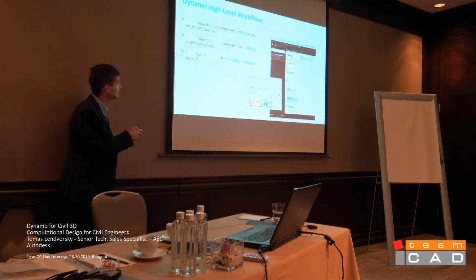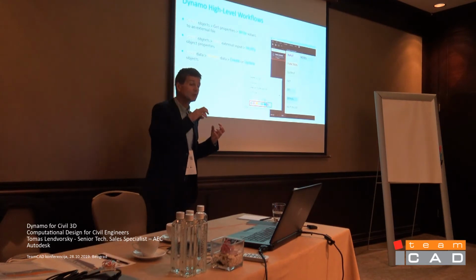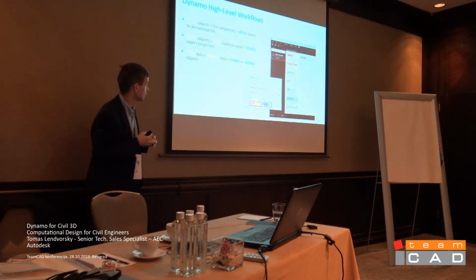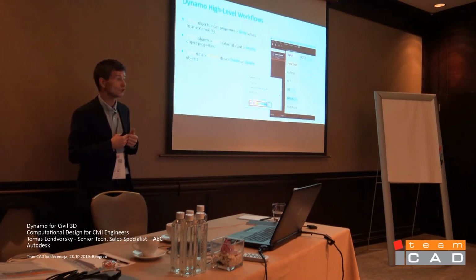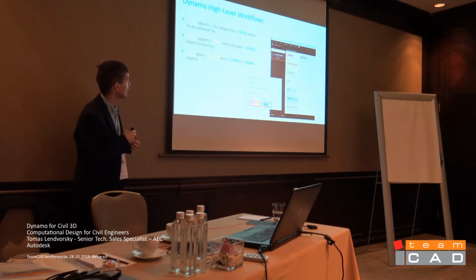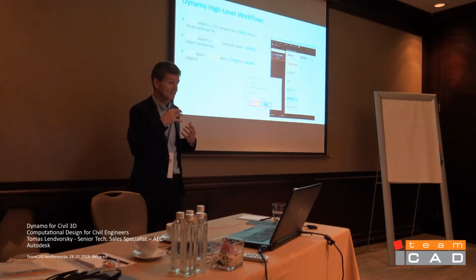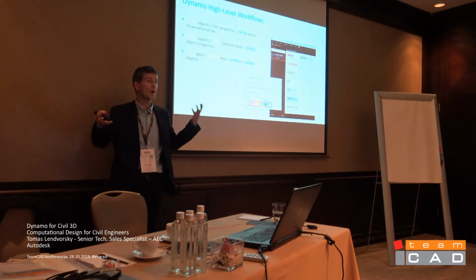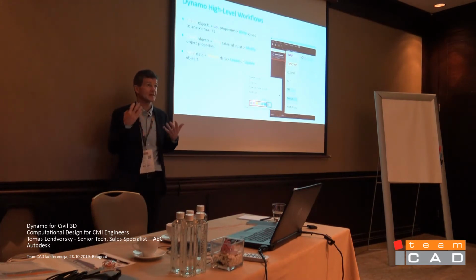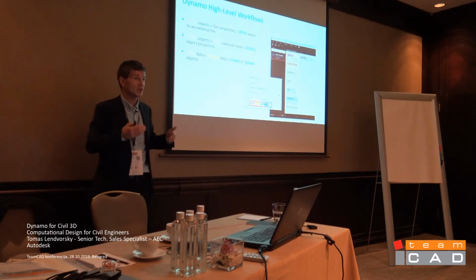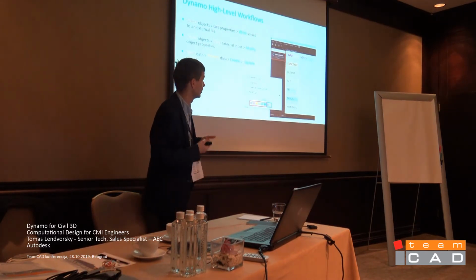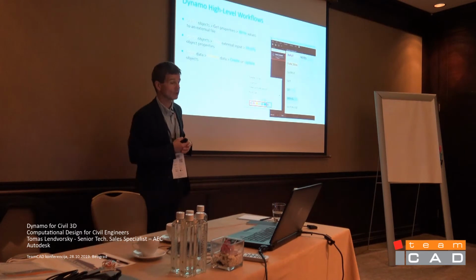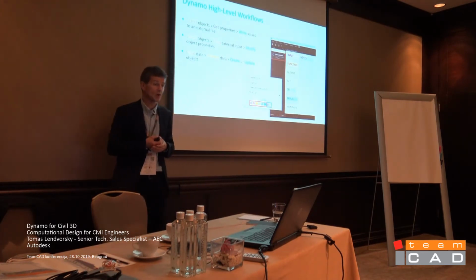Or you can select objects, read some input information from outside, and modify, for example, object information, object properties. It's another example of what you can do with Dynamo. And the third workflow is you can input some data, process this data, and either create or update what already exists, which is maybe the most common thing, because you want to create some new objects. So basically these are three high-level workflows which you can do with Dynamo at this point.